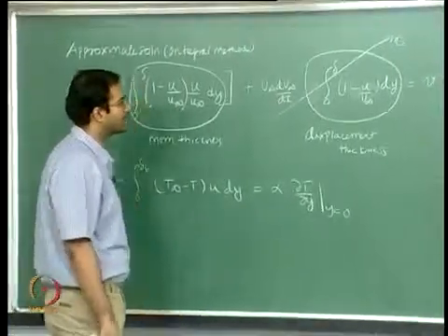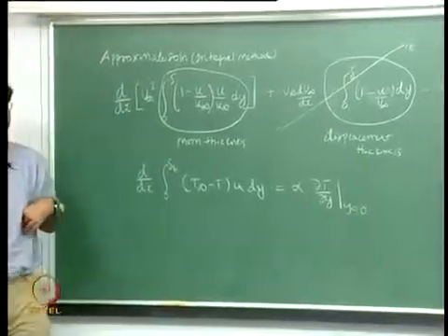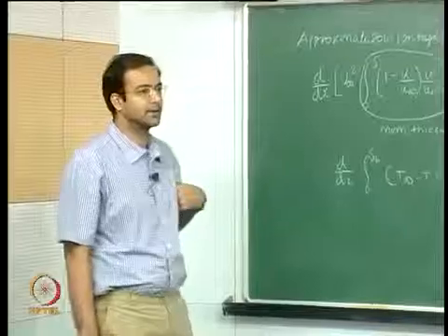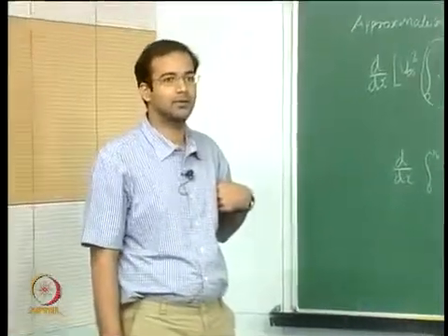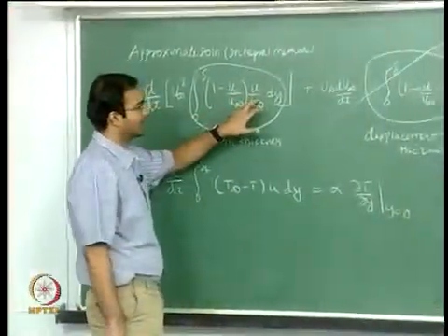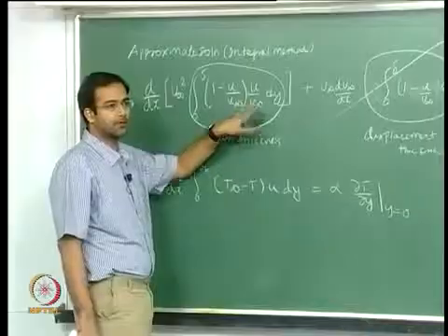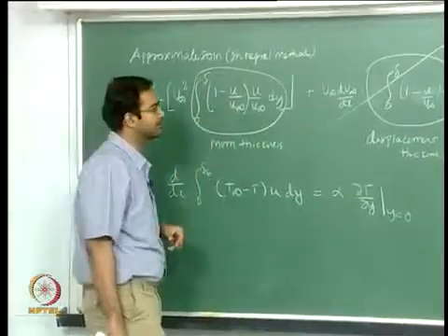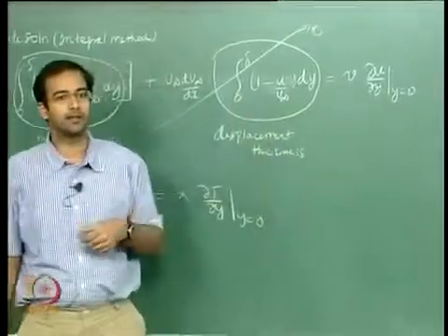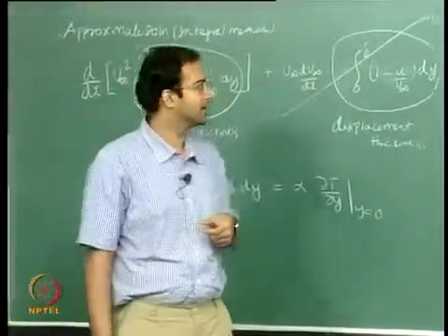And why we are using the integral form here is that we will guess some approximations for velocity in terms of some polynomials, maybe linear or quadratic, cubic, fourth order, whatever. We will substitute that into this and integrate it out over the entire boundary layer thickness, and we will find an expression for calculating the boundary layer thickness delta from here.